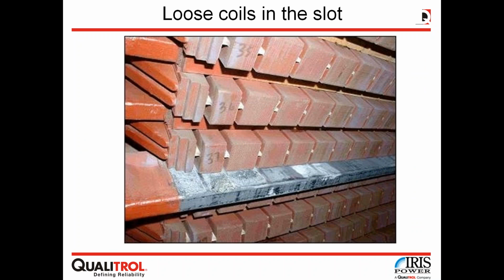Okay. Surface insulation. If you're talking about stator winding, then we are not measuring that gap, but the gap will affect the amplitude of the pulse. In other terms, if the gap is bigger, we are going to have a higher amplitude pulse. When we analyze PD results, we look at both the number of pulses per second and the amplitude of the pulse.